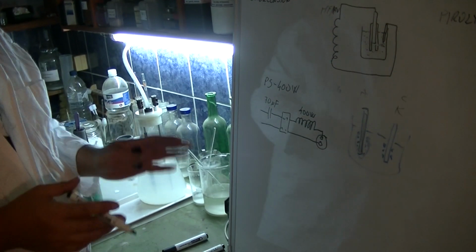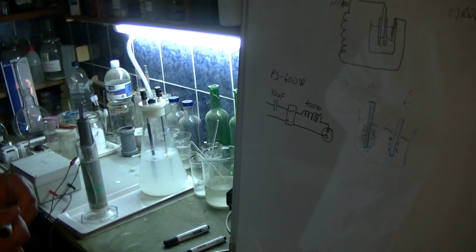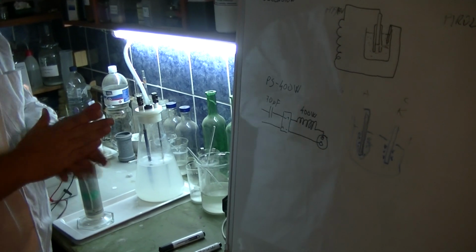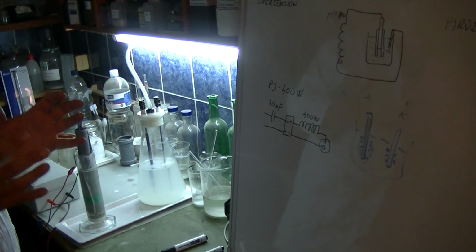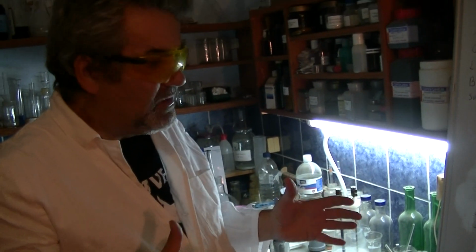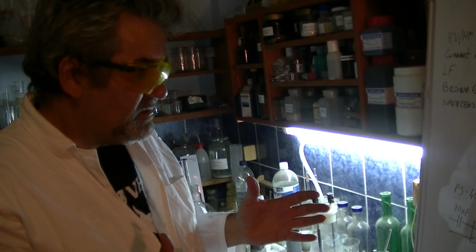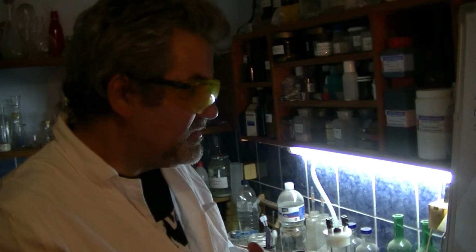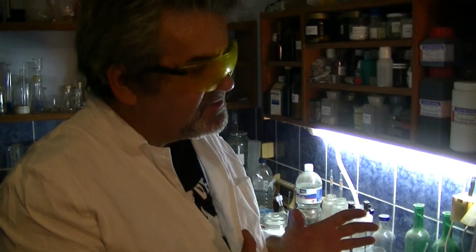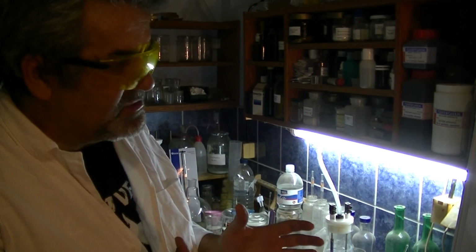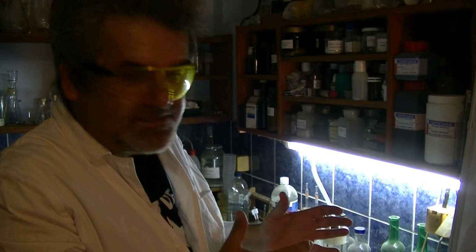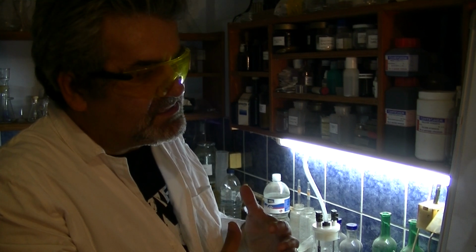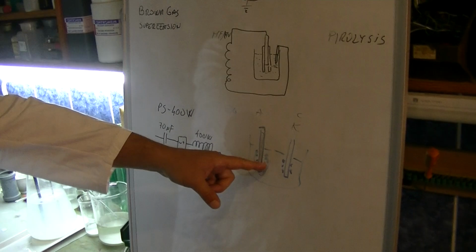Which means that Faraday's law is correct only while we are working with small amounts, not when we increase to the extreme. If we have no extreme parameters in the electrolyzer, then Faraday's law is correct. But when we increase, a new phenomenon comes, and it's easy to check.